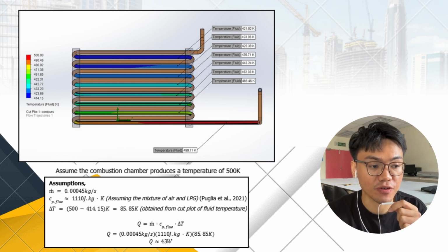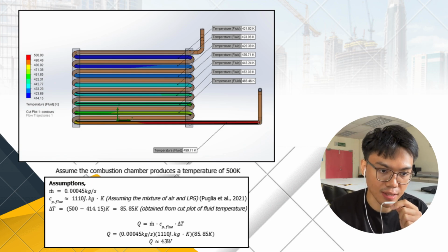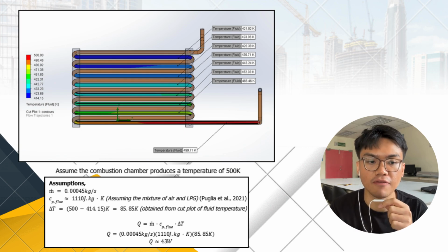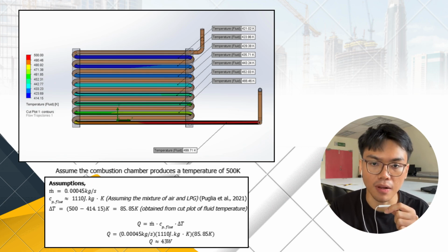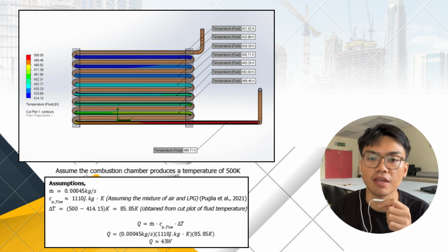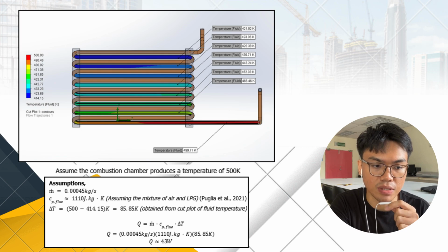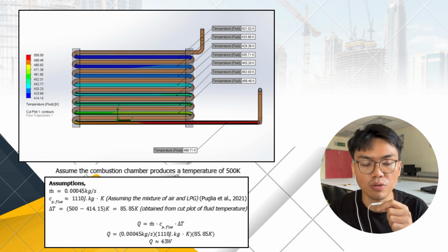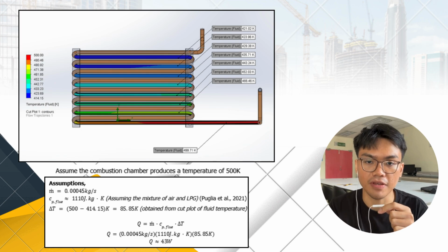This slide focuses more on the radiator model, which is our main heat exchanger in our LPG drying system. The radiator pipe has a 10 mm outer diameter and an internal diameter of 9 mm, so it has a thickness of 0.5 millimeters, and this pipe along the radiator carries the hot flue gas from the combustion chamber, while the external radiator fins transfer heat to the surrounding airflow before the air enters the drying chamber. There are a total of 30 cooling plates with an 8 mm spacing, which improves heat transfer through conduction from the pipe to the fins, followed by forced convection from the fins to the air.